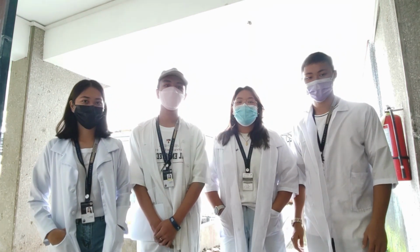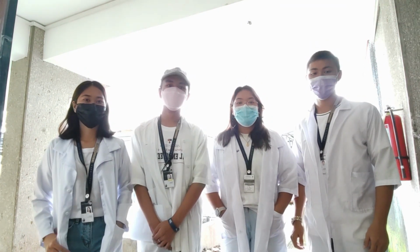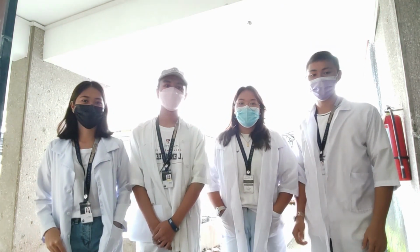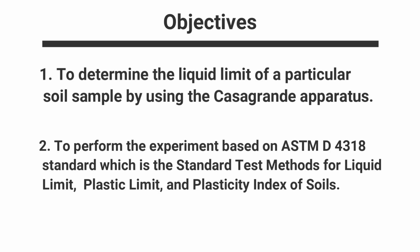And today we will be performing experiment number 8 entitled Sieving and Liquid Limit by Casagrande Apparatus. The objectives of these experiments are the following. First is to determine the liquid limit of our particular sample by using the Casagrande apparatus. Second is to perform the experiment based on ASTM D4318 standard, which is the standard test methods for liquid limit, plastic limit, and plasticity index of soils.